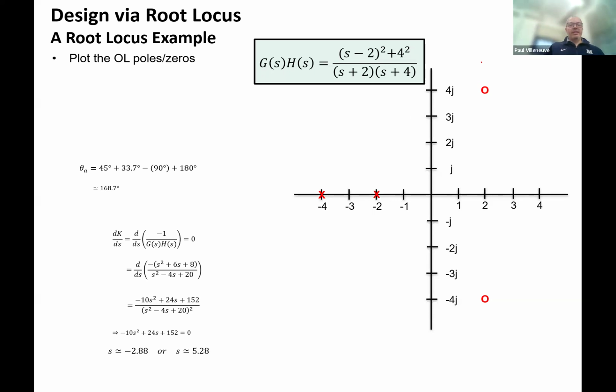So the root locus rules, let's start with the easy one. We plotted the poles and the zeros, finite poles and zeros. Now we've got to use some intelligence, and we recognize that we have 2 finite poles and 2 finite zeros. So do we have to calculate any asymptotes when our poles approach a zero at s equals infinity? No, because we're going to terminate at finite zeros. So theta A and sigma A are invalid, not necessary to calculate those.